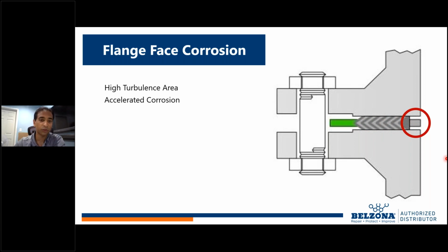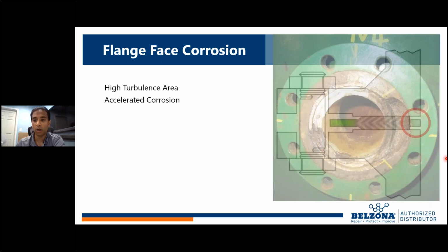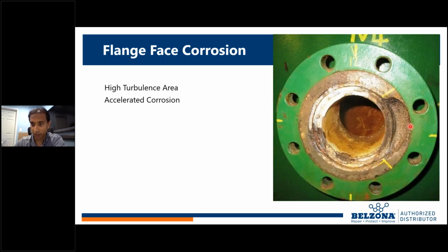This is pushing against both flange faces. Well, if you start removing the flange face there, you're going to weaken the seal there. And what's ultimately going to happen, you're going to see process fluid pass right by that gasket. It's not going to work anymore. And so here's a visual representation of that, where the process fluid started working its way. Here you have the gasket seating area. And look, we penetrated right by that. And we're going to start seeing some process fluid spray right outside the nozzle itself.